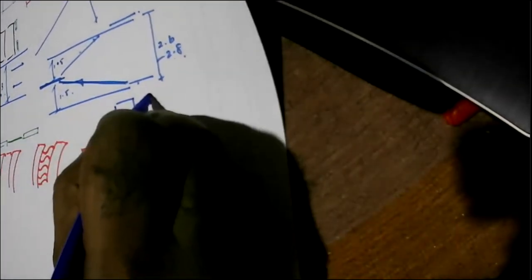If you take two cardboard boxes, one is like this, the other one is like this, A and B, A will be much stronger than B. So when you have a situation like B, we connect it with a structural element like a beam, so that it behaves as if it is closed.